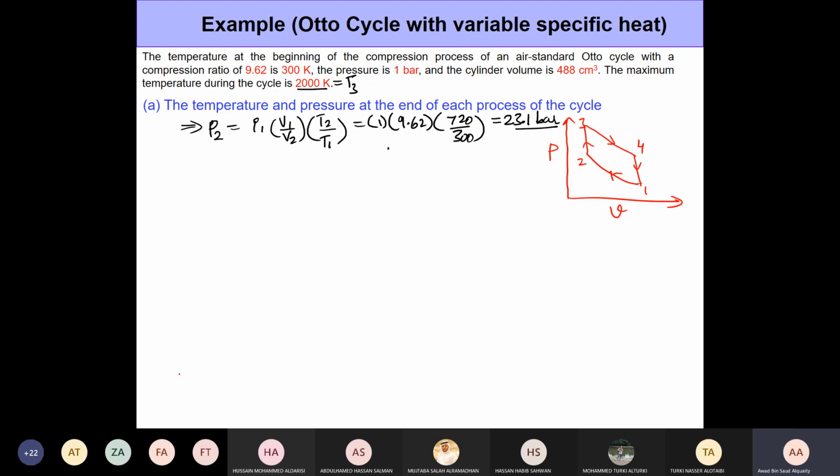I hope things are clear to everyone. And for those of you who answered the pressure should be reduced, the thing is, at this stage, things are not so clear to us, right? You cannot just look at the engine and it's not very obvious what you need to do to increase the efficiency. How exactly we approach increasing the thermal efficiency is not very clear. That's the whole reason why we bother about doing an analysis, right? A simple analysis to start off with, to give us a better idea about what the parameters are. So just by looking at it, we could think that maybe I should reduce P2 a little bit. That'll reduce my work input during the compression process, something like that, right?